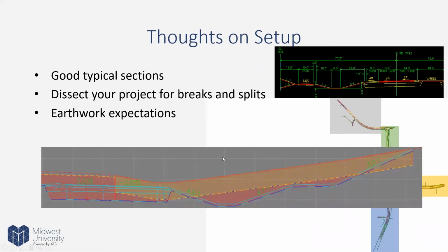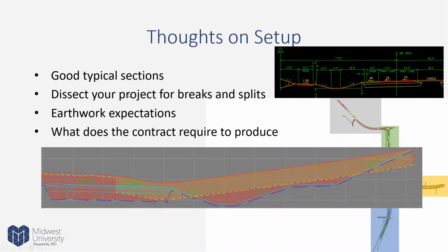Before you get into the earthwork, definitely think about your earthwork expectations, what needs to be the outcome at the end before you get too far along defining all this information, because it does take a while to get there. But again, you're going to get good numbers out of this. And then what is the contract required to produce? When you're going through all this information, is that datum surface going to be part of your submittal? I think we're seeing this more and more now, that contractors and given agencies want to have some of these surfaces to work off of, to either do machine grading or to do staking from. So it's important to know how much effort you need to put in to make a good surface out of these.